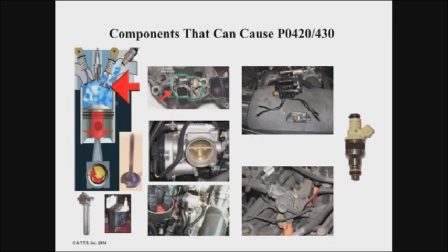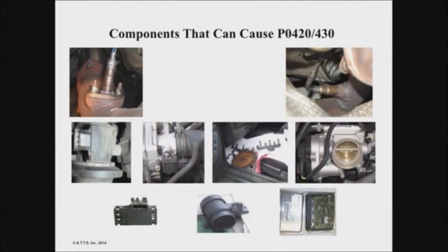Well, let's look at the top left-hand corner. How many of you guys have replaced that oxygen sensor of that type of style? How many times is there a problem where that is not seating correctly? And you go, I can't see it from where I live. That little leak ain't going to matter. It's going to matter, correct? Or little cracks around a regular oxygen sensor. Mass airflow sensors. You know you've never come across a mass airflow sensor problem, right? Of course you have. But you need to know how to check them and see if they're good or bad. Sometimes computer problems. Cam and crank type sensors. Anything that causes fuel control issues.